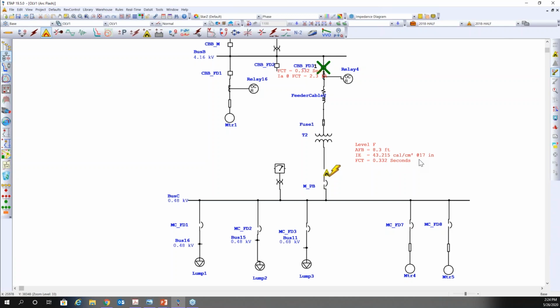We've implemented some protective measures with some of our OEM customers who put a recloser up here, and with that recloser, you had an arc flash relay here, and you interlocked it with pressure, to operate that arc flash or recloser to actually lower this down to a reasonable level.